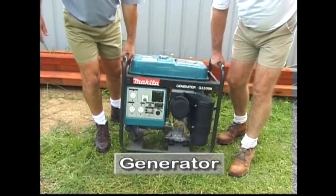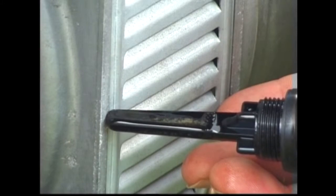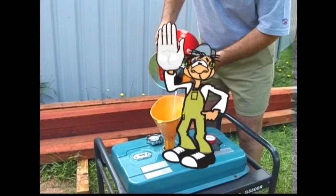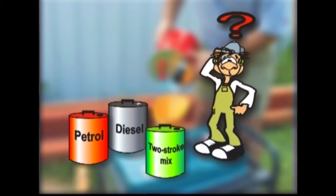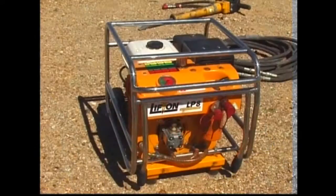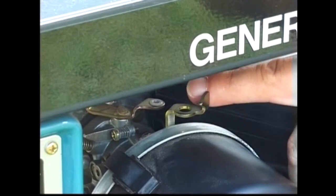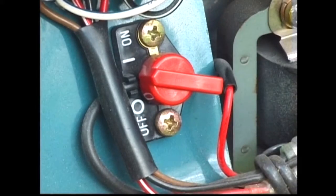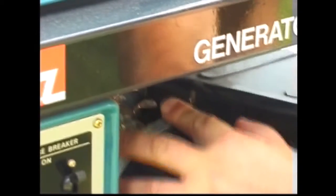Generators should be set up on level ground. The oil level must be checked and topped up if required. Before fueling any machinery, it is important to check what type of fuel is used. Most combustion engines have similar starting routines. To start the generator, the fuel is turned on. The choke is turned on, and the switch is set to the on position. Once the engine is started, the choke is returned to the off position.